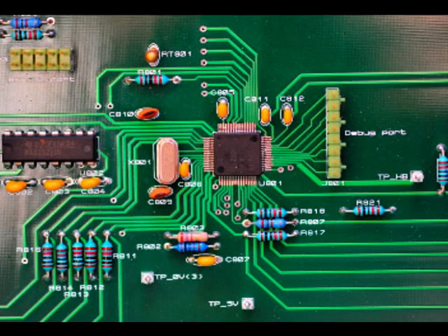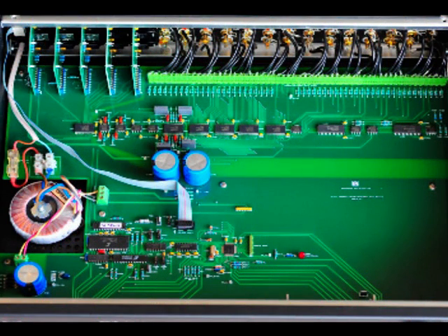Because the microcontroller has a pin pitch of only 0.5 mm, which is difficult to solder by hand without special equipment, I had my friends at Elf Electronics solder that chip and a few other surface mount ones to the main board. The 7 boards are then installed in an aluminium enclosure, a fairly fiddly process.